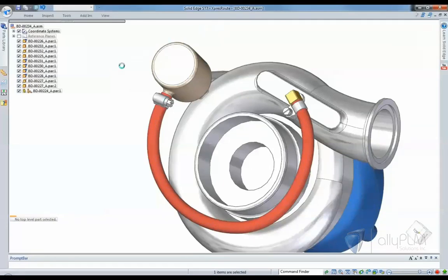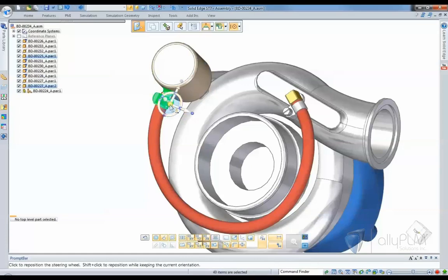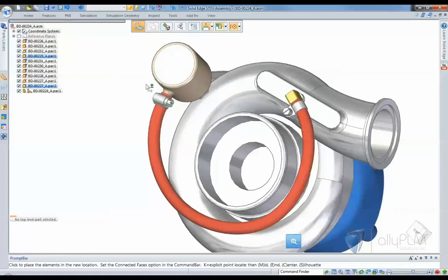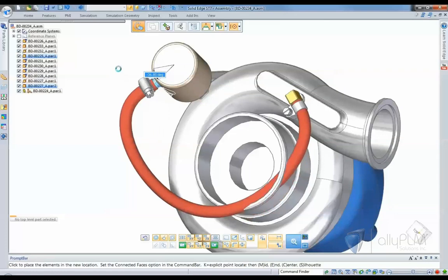Once the length is locked, like we just did, we can also select how we want the curve to respond during an edit, and then finally we can go back in and change the location of the port one more time and see how the fixed length curve responds as we rotate the wastegate. If you notice, you can see the hose now maintains the length that we just set.